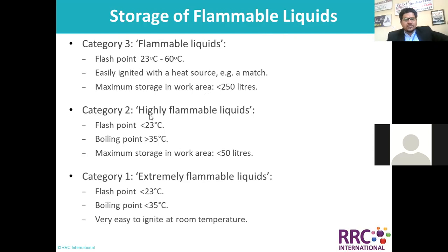If category 2, highly flammable liquids, the flash point is below 23 degrees and the boiling point is above 35 degrees. So maximum storage is below 50 liters. So the higher the flash point or boiling point, the less should be the volume to be stored.